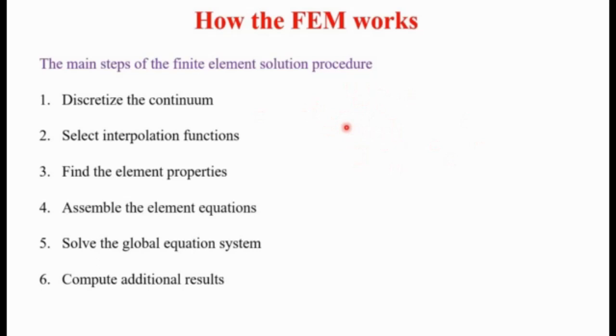Then the finite element mesh is typically generated by a preprocessor program. In finite element analysis, there are three main phases: the first is called the preprocessor, the second is the solution, and the third is the post processor. The first step, discretization of the problem, comes under the first phase, the preprocessor. The description of the mesh consists of several arrays, which are nodal coordinates and element connectivities.